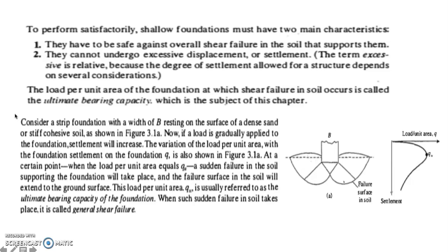So basically, to perform satisfactorily, shallow foundation must have two main characteristics. They have to be safe against overall shear failure in the soil that supports them. They cannot undergo excessive displacement or settlement. When we talk about excessive, it is relative, because the degree of settlement allowed for a structure depends on several considerations.